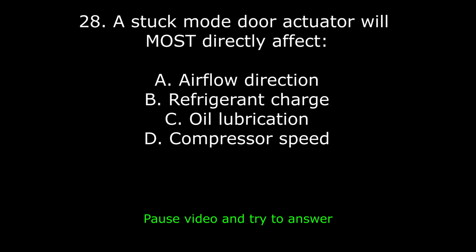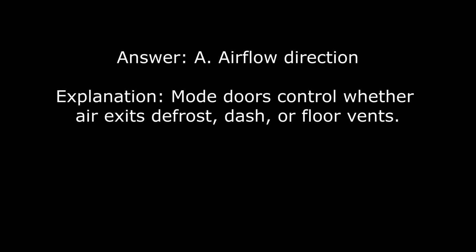28. A stuck mode door actuator will most directly affect A. Airflow direction. B. Refrigerant charge. C. Oil lubrication. D. Compressor speed. Answer A. Airflow direction. Explanation. Mode doors control whether air exits defrost, dash, or floor vents.